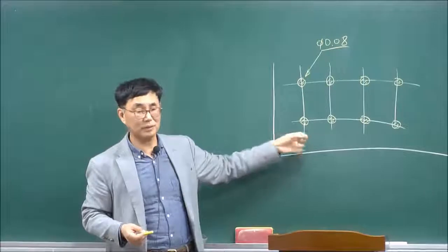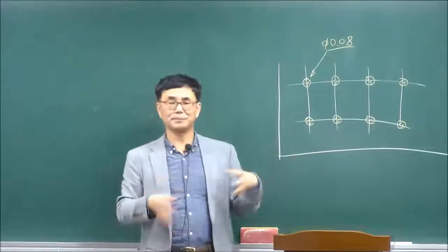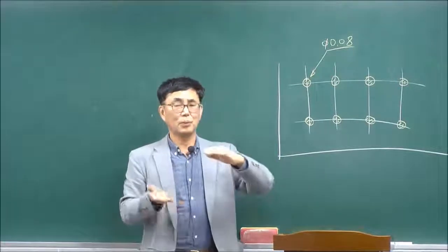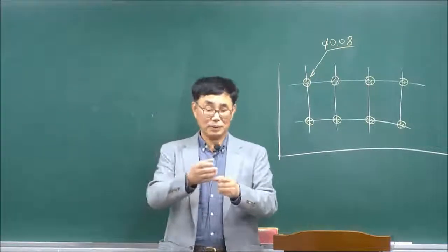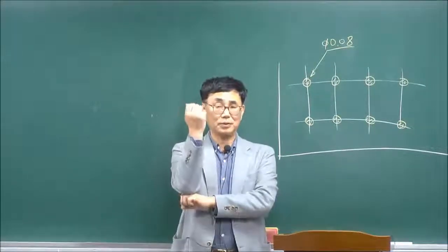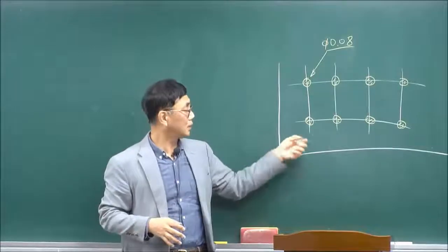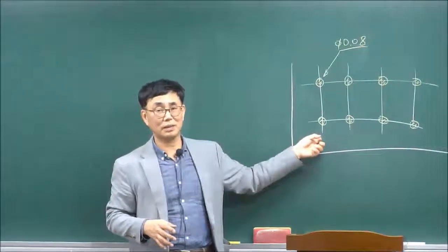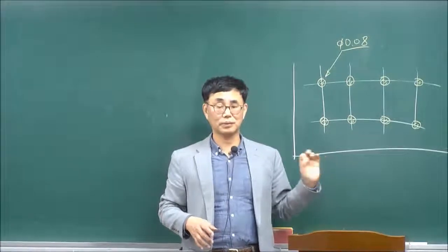Very reasonable. Also, if you assign true position within the bottom surface, then it is also assigned perpendicularity of the holes. So this is a very, very clear definition for the true position of the hole centers.